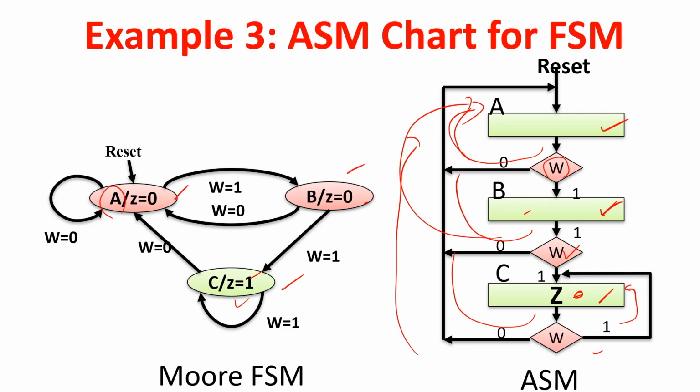In state A getting a 1, go to B. In state B getting a 1, go to state C. In state C getting a 1, you stay in the same state. So, the problem of detecting a sequence of two 1s can be modeled using ASM.